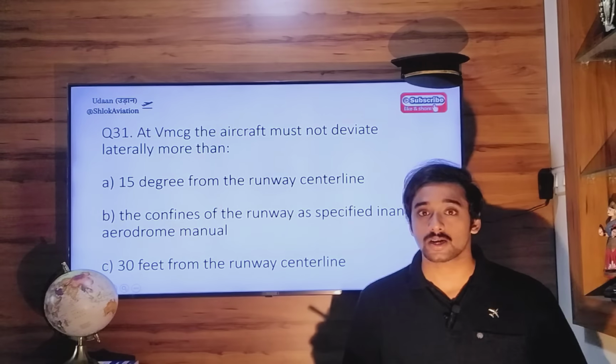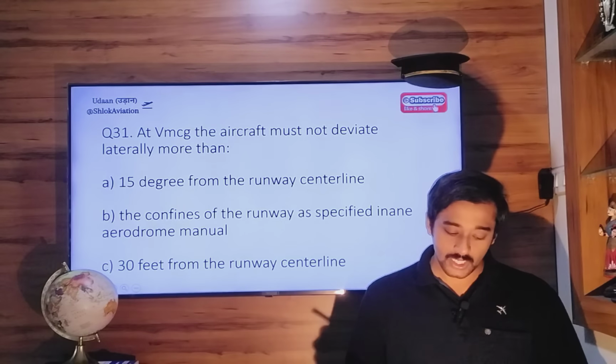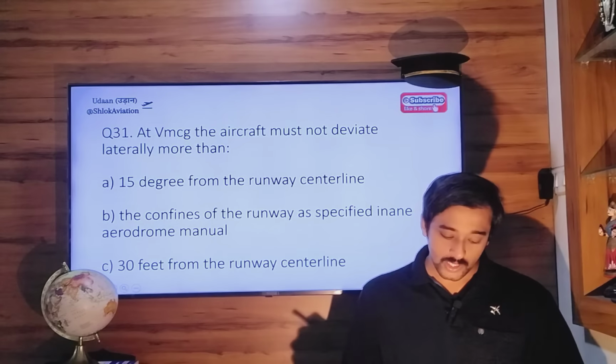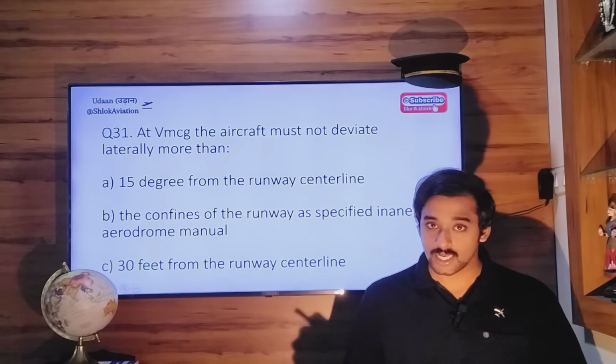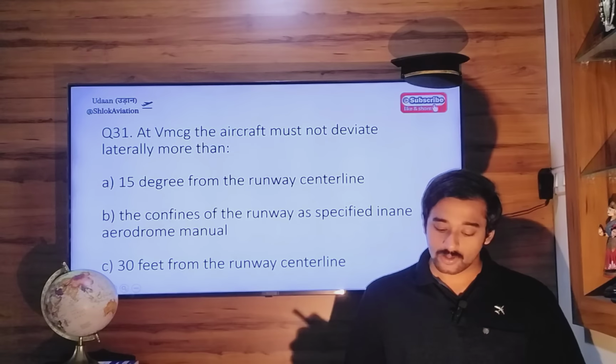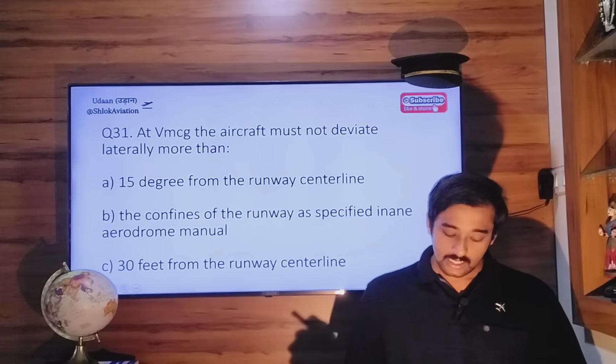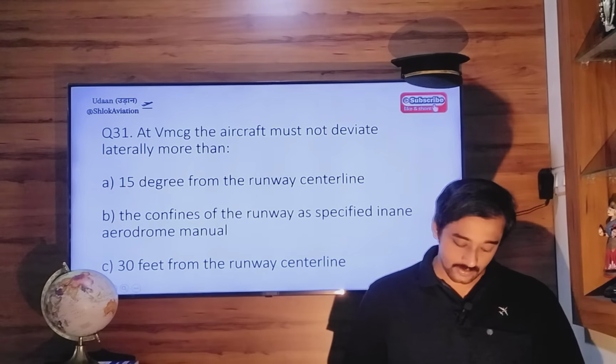Of aircraft on the ground. Aircraft must not deviate laterally, that means sideways, more than 15 degrees from the runway center line. Confines of the runway as specified in the aerodrome manual, 30 feet from the runway center line.